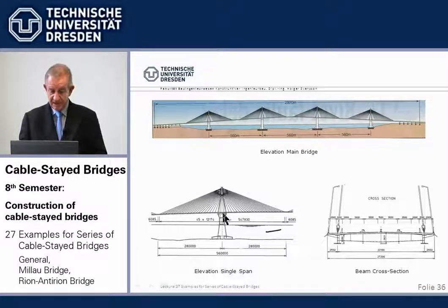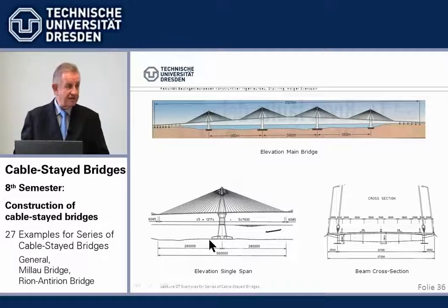pier underneath. So the bending, the force couple which comes here, is taken in bending in this pier shaft. And then the pier shaft has a foundation which is circular, wide enough so that it is a raft foundation. It's a flat foundation which sits directly on the soil. However, the soil is very specially prepared, and there's then the trick with the 2-meter sliding.